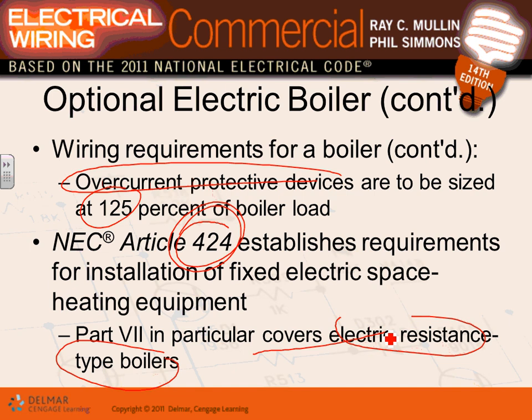Mechanical radiators will radiate the heat in. That's one way of doing it. The other way, Adam, later on, next project, they send this hot water into something called an air handling unit. Like in our building, the air handling unit is nothing but pipes full of hot water and a big blower fan that blows air right through the hot water coils, mechanical coils. They're full of hot water. So if you blow air through a coil that's hot, what do you think you're going to get from the other end? Hot air. That's how you get hot air in a commercial building. We will go over that one, guys, in another chapter too.